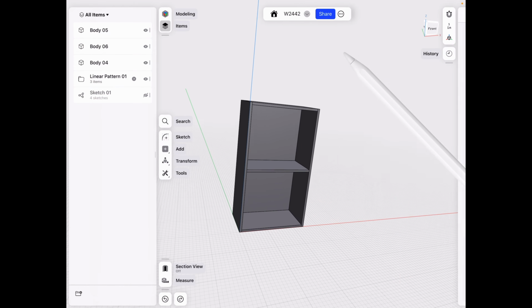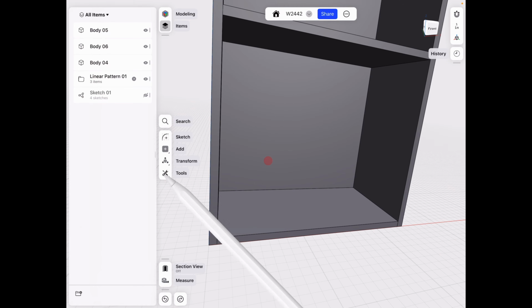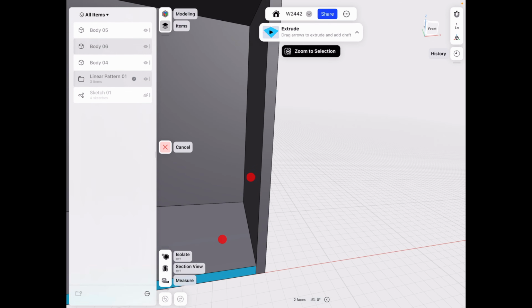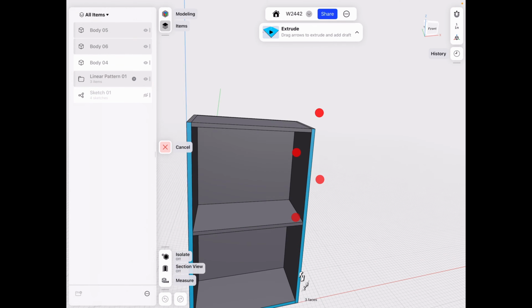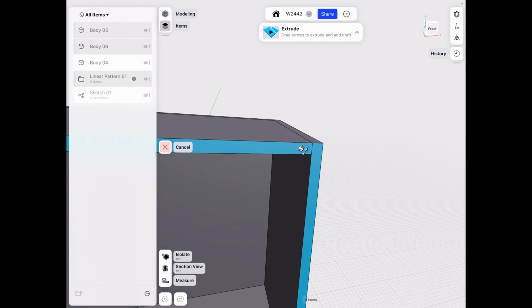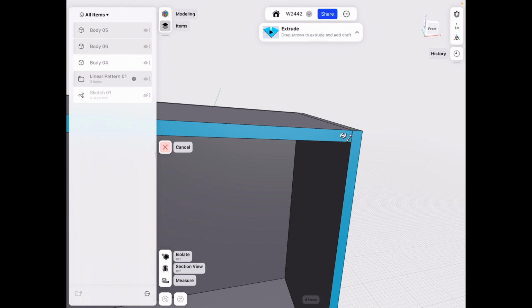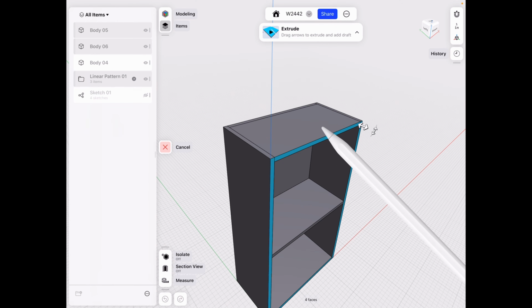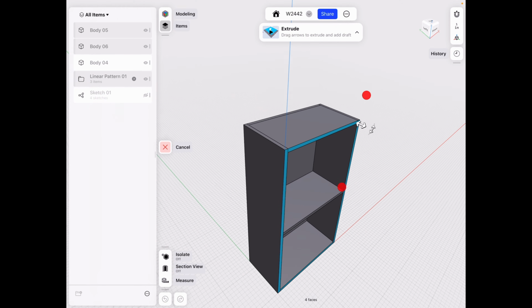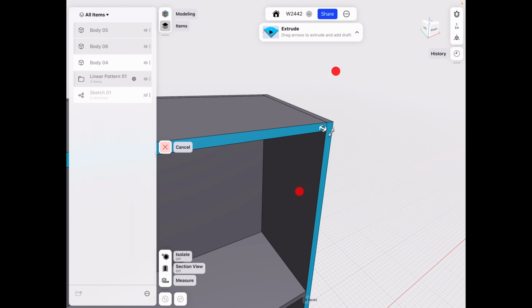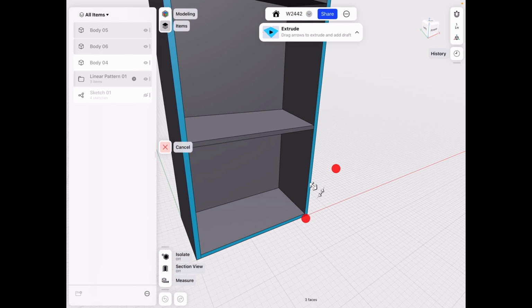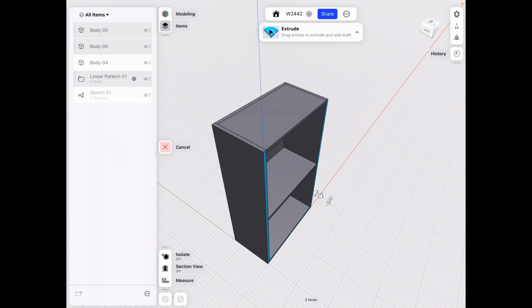Okay. Once we have this, we need to go to Tools, Extrude, select these 3 faces, and not the top one, because if you change the pattern, this one becomes only the third piece of the pattern instead of the final one. So you actually cannot extrude that out because it will break your history. Okay, so this is why history is a bit complicated unless you practice.